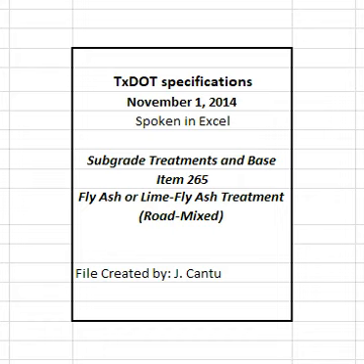4.3.3 Application of fly ash. Uniformly apply FA in dry form unless otherwise approved. Apply at the percentage determined in section 265.2.7, Mix Design. Apply FA only on that area where the mixing and compacting operations can be completed during the same working day. Do not use a motor grader to spread FA. For LFA treatment, begin FA application within 4 days after the lime mixing operation has been completed unless otherwise approved.